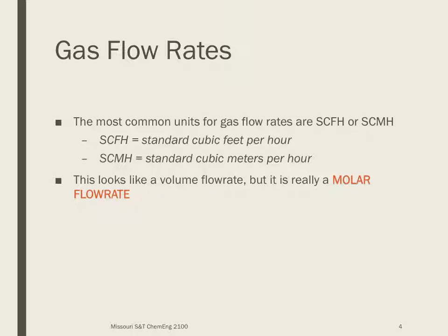Now, this is deceptively looking like a volume flow rate. But this is not describing volume. It's volume if the substance happened to be at the standard temperature and pressure. But it's never at that temperature and pressure. So really what this is doing is it's describing a molar flow rate. So let's look at an example to see how this is applied.